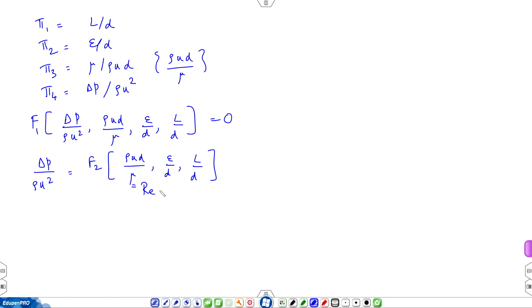Now, with reference to our energy equation, you know that delta p over rho is pressure head, u square over 2 is the kinetic head, and g z is the gravitational head. Is it not? All three together will represent the mechanical energy of the fluid at some location. If you want total energy, what do you have to do? You have to add internal energy to it.